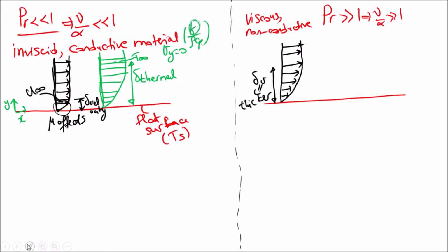Okay. But if you look at the thermal boundary layer, you will have something like this one. Now the alpha is small. Alpha small means the conductivity is small, and we know that in the y direction velocity is 0. It is transferred only by conduction, and therefore this conduction heat transfer only affects a small layer here, and the rest is T infinity. This part is T infinity, and this is the thickness of the thermal boundary layer, and this one is thinner. Okay.